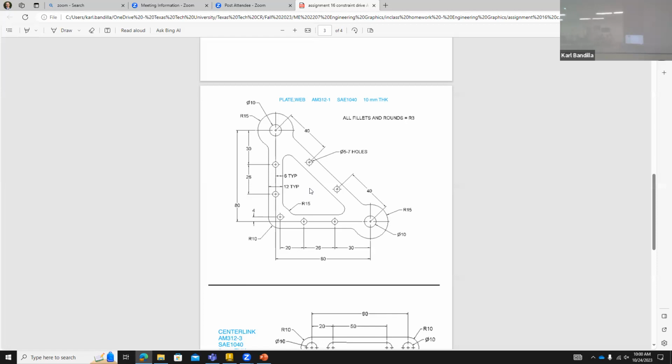And then, of course, where would you start? I usually start at that point right there. If you have this point, you can draw this first big circle, and then you can draw that bar going out there, because the center line is the same center right here. What's the thickness of the bar? 12, and it's at the center. Once you have that, you can draw yourself a line at 45 degrees and mirror it, or you can just draw the rest as well.